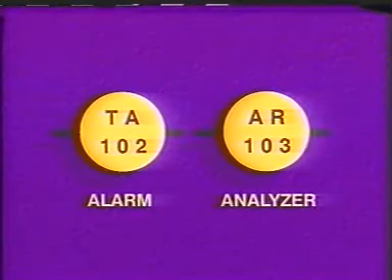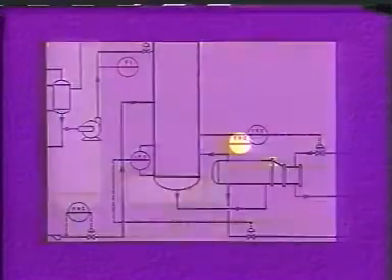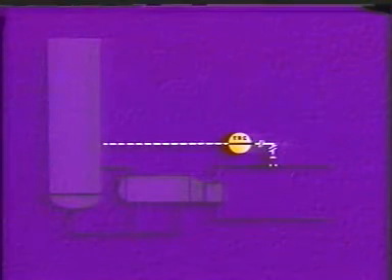Process piping and the walls of process vessels are usually shown as solid, unbroken lines. The lines supplying air to process instruments are shown by short diagonal marks crossing a solid line. Here, a valve is connected to a controller by an air line. Electrical signals and electricity supplied to instruments are indicated by dotted or dashed lines.